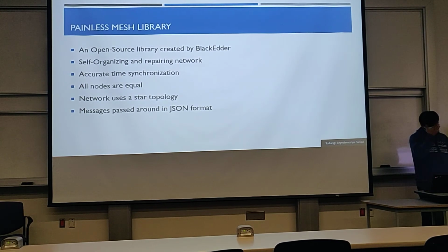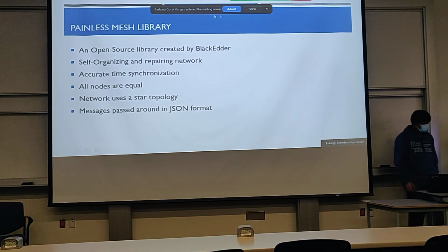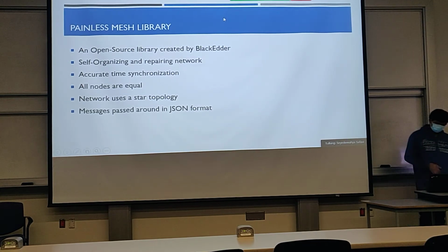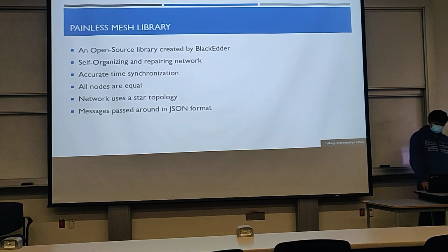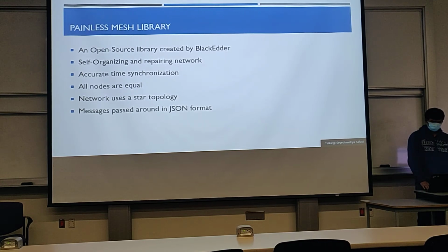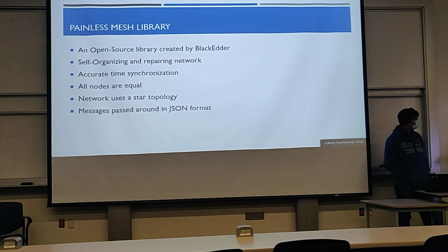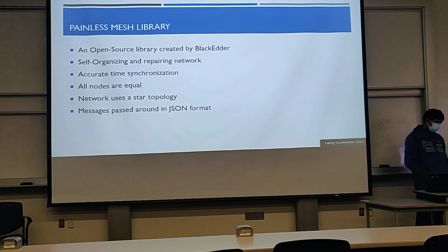So this project was implemented using an open source library called Painless Mesh. It's a self-organizing and self-healing ad hoc network that has accurate time synchronization. In this mesh network, all nodes are of equal priority, and it uses a star topology to establish the mesh. The messages are passed around using a JSON format so that the messages and the instructions can be combined into a single packet and sent out.